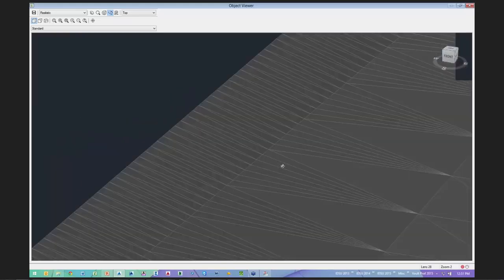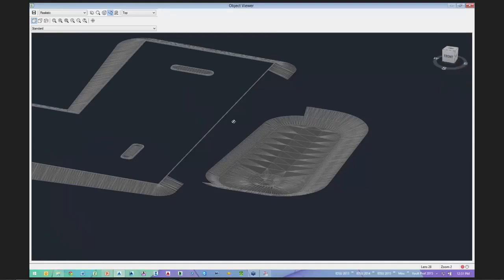Okay. So we're daylighting up there. Now what we have is just this area to fill in here. And here's where putting the curb in the same site and the same surface as this pond works pretty nice, if you have a simple enough scenario like this, because we can again use the infill concept that we did down here. We can use this in this area if we just close off these gaps here with feature lines. So what does that look like?